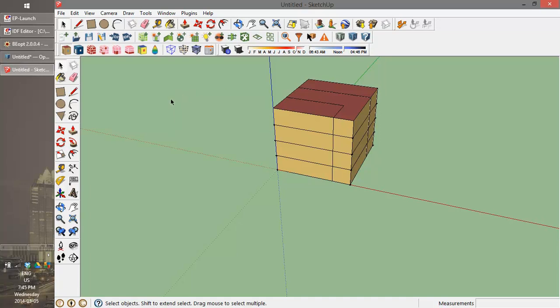So I just want to put some windows on this building. So it says switch the render mode back to render by surface type. So I'm on render by surface type. Select all spaces by drawing window. Select tool. Okay.